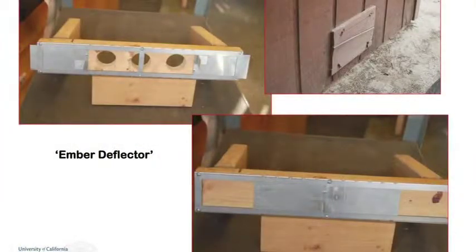So these vents, the Brand Guard, the Vulcan, the Fire Guard, these are passive. You don't need to do anything, they work. You don't need to do anything for them to work besides put them in. If the Vulcan vent activates, you have to maybe replace the vent. If the Fire Guard vent trips, you're going to have to reset it. But in order to make it work, you just need to put it in place and it'll do its job.